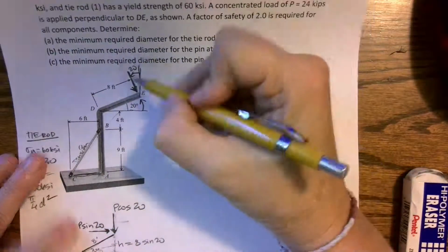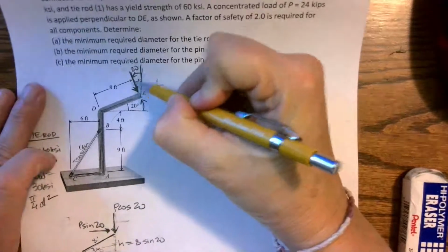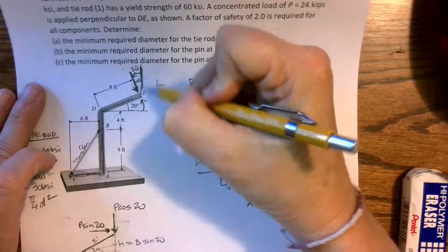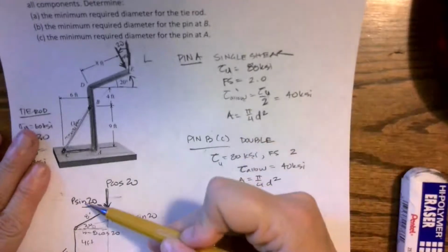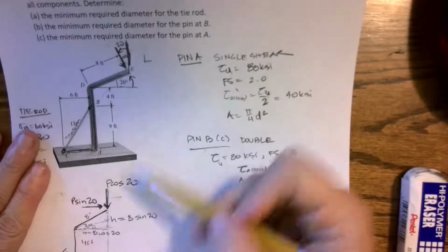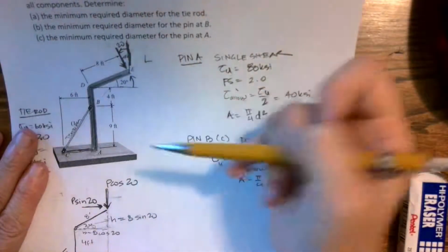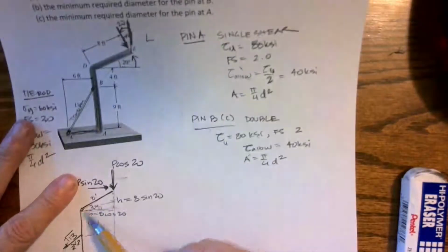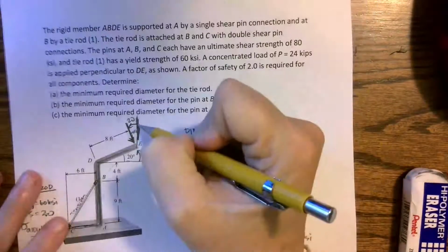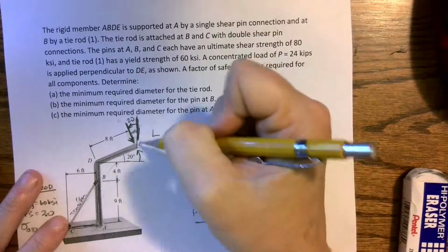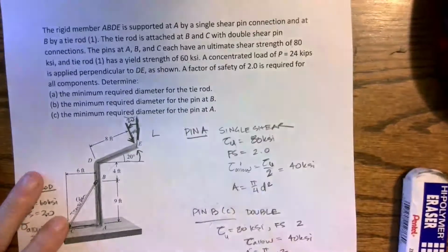The adjacent to this 20 degrees, so the adjacent will be the Y component. Remember, you can't just say X components are cosine and Y components are sine. You have to look at where it's being rotated from. When we found it from the height, we were being rotated from the X-axis, so it is cosine, sine. When we're finding the force, it's rotated from the y-axis, so it's going to be sine, cosine.